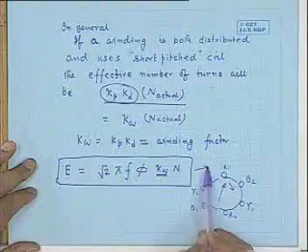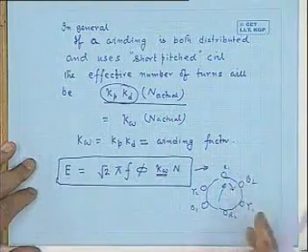There will be several coils separated by an equal angle like beta and connected in series to make an R phase. Similarly, for the Y phase, everything will start after 120 degrees and will have several coils distributed in space. So there I have to take that angle into account and calculate the effective number of turns.